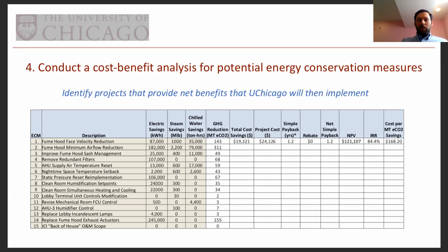We're doing campus-wide projects around lighting or insulation. There are different things related to steam or electricity consumption. And an interesting project we're evaluating at one of our lab buildings, where we have cooling towers and their own chilled water plant. They use a lot of water, so it's not necessarily energy, but it's water. We're evaluating a project where we take all the outside air that we're cooling during the summer, take the moisture out of it, the water out of it, and then use it for makeup water in the cooling tower.